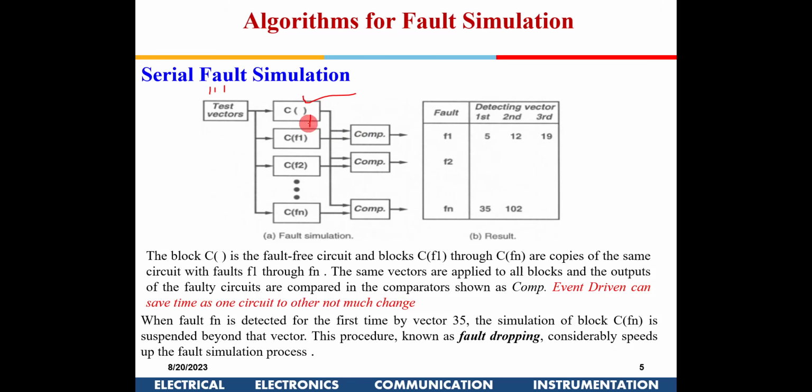When I am coming from the first to the second block, the results at several nodes are already available to me. Now I am just changing some data somewhere in between. These test vectors are also the same. So I will take that change as an event, and I will compute the output again.